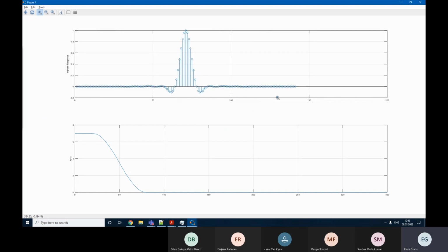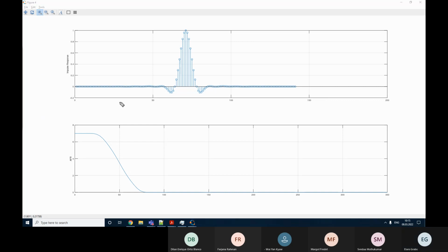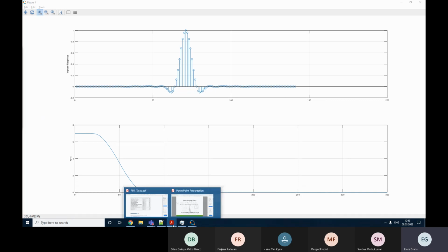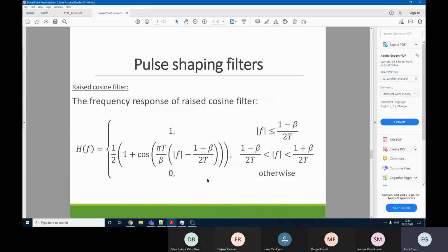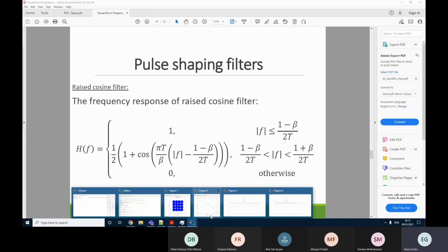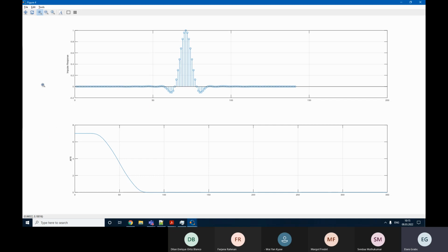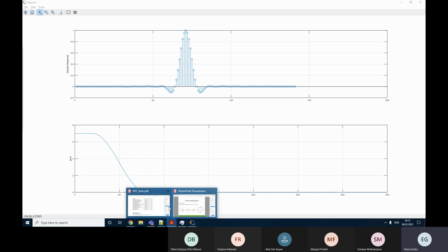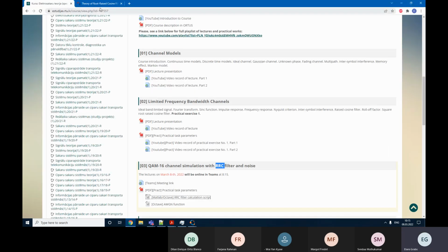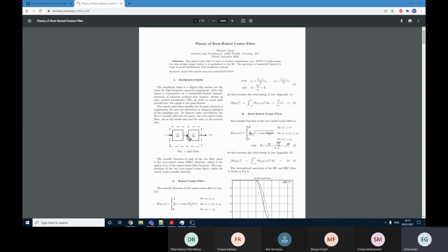And this plot is twice as long because we calculated the convolution. So here, instead of calculating this filter according to the formula given in the lecture, we calculated the total filter response, which consists of 2 parts. We calculated this response by connecting 2 filters in series.